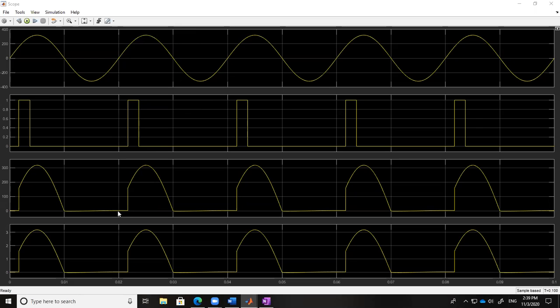So your device starts exactly after 30-degree. The moment there is a 0 voltage, the device stops conducting because the current is also 0, right? And current is just following the voltage. Resistance is 100 ohm, so voltage is divided by 100. That is your current.